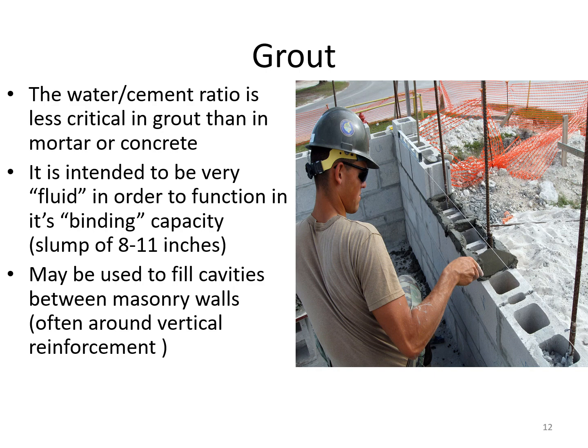Otherwise, there's always some moisture that gets through the brick, and without a weep area, everything would be in contact with even the moisture barrier. Even if you had that, it would still transfer moisture right through to the wall assembly. And like I said, if you have a 2x4 wall assembly or a 2x6, all that moisture would be transferred. Never mind the thermal items that would be transferred through the wall. So the weep area is critical.